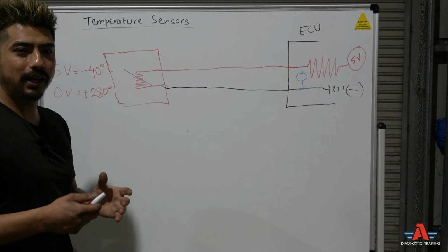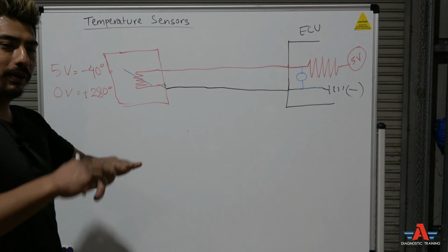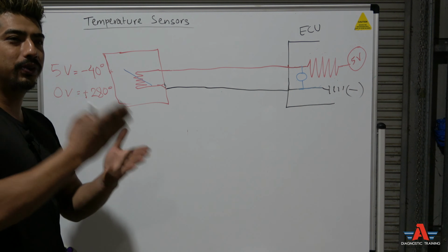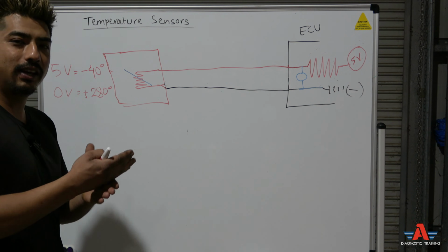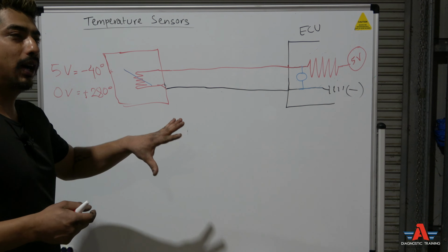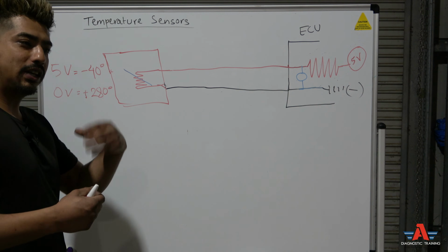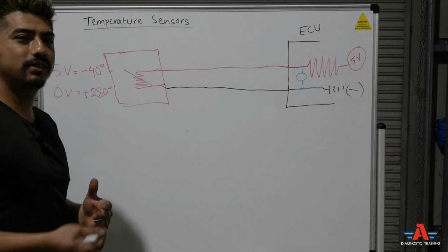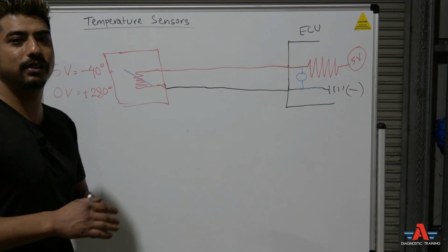That would be a little bit more complicated diagnostic, but usually if it's a circuit fault, the fault is happening right there and then, unless it's an intermittent problem, right? But if it's a hard fault, as soon as you clear the fault code it comes back on straight away. Usually that's a circuit fault, a hard fault. They are very easy to diagnose.